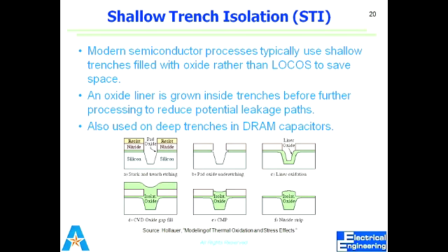So in this case you can see that we can have a thick field oxide as compared to my active area, that is the gate oxide. So this is a good approach to have a thicker field oxide as compared to my gate oxide, that is shallow trench. You get a trench, and after that you under etch that oxide layer, and then you deposit. After deposit, that trench actually fills up with the deposited silicon dioxide, so you have a thicker layer of oxide in the middle. You don't have anything at the other side, because the growth actually grows in both ways. Deposition will deposit everywhere, so just like a blanket deposition in the hole, you will be having a thick layer of oxide.